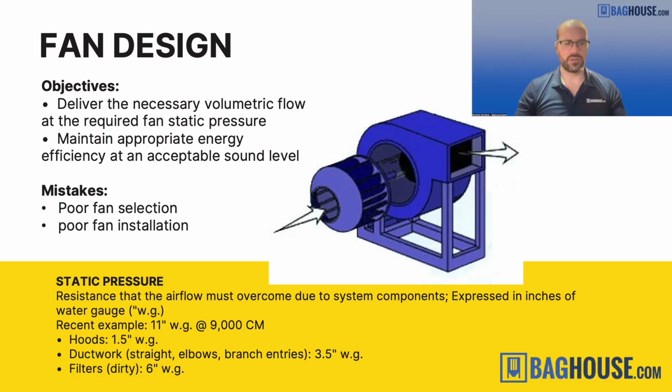We can take the ductwork and we can calculate that to pull the air through all of this ductwork will create this many inches of static pressure. And the inches there is inches of water column or inches of water gauge. This is a measurement for resistance. It's also a measurement for vacuum and pressure that's used.